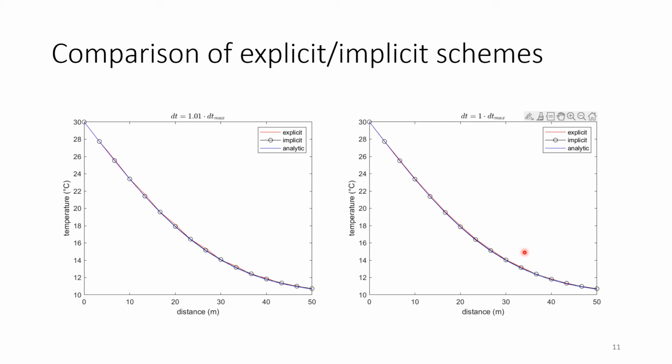So I will do a bit of a recap here. We'll talk about stability in detail a bit later, but what we can already see is that an unstable model is defined by the existing error, so the difference between the numerical and the analytical solution, growing over time. All those simulation results I showed you here are shown at the exact same time. And this is by definition still unstable.